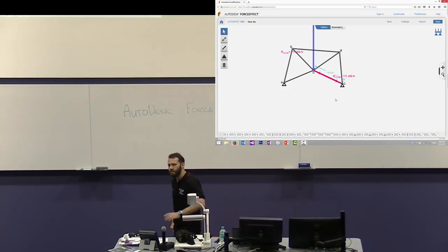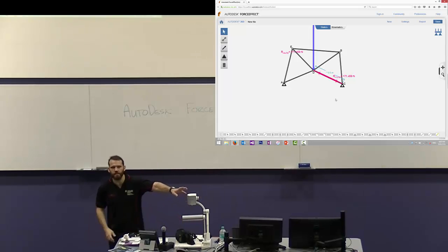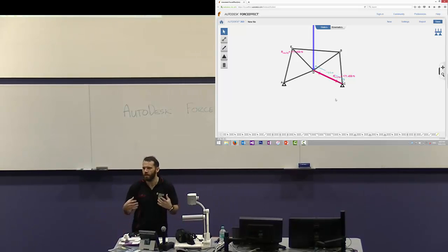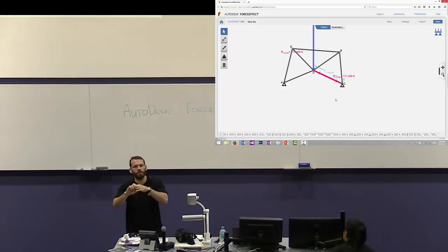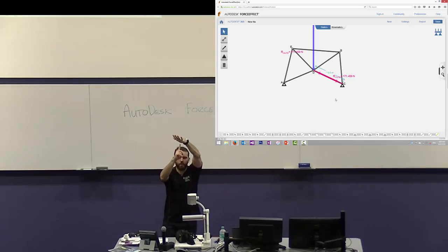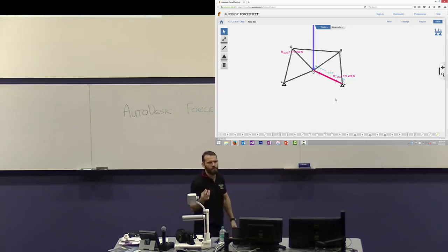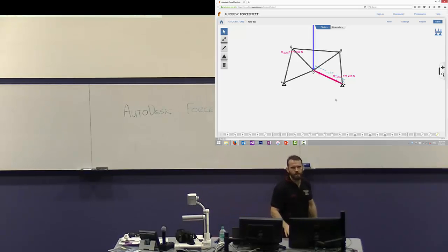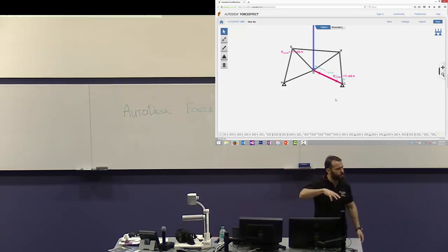Okay? And now that's not definitive because it's a very simplistic tool, but it gives us a starting point for how big the material needs to be, what materials we can use, particularly what glue or bond at those joints. You don't want to just hold that member, you will probably want to use one of the joints that you're actually planning to use at the top and hang the weight, because in most cases it might not be the actual member that'll break, unless it's really light material. It'll probably be the way you fix it to something. So you can test both the member and the way you're gluing things together to really optimize that process.